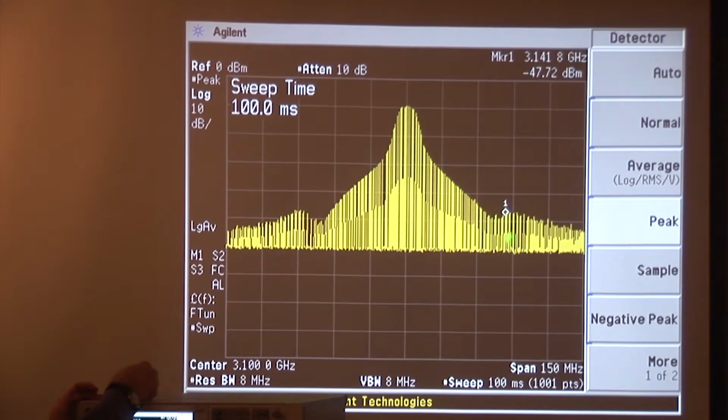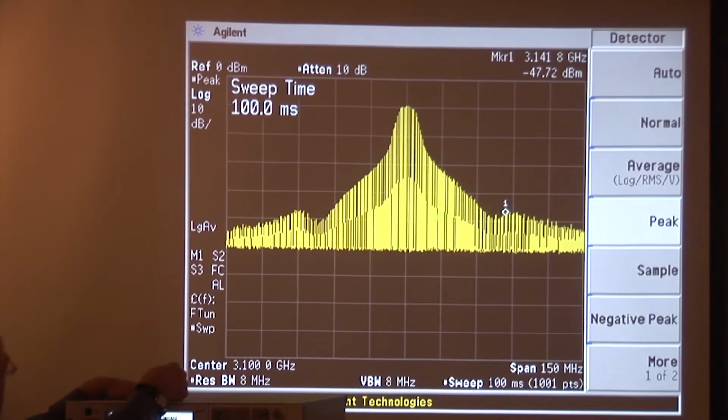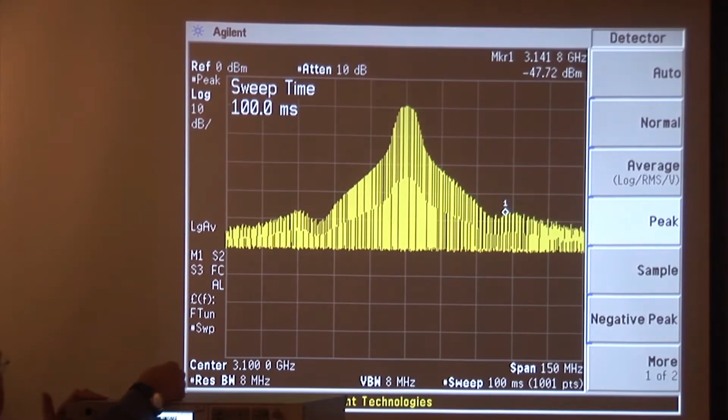And the peak detector will latch up to the highest level that occurs in any one of those bins while we're sitting there in this maximum hold sweep mode. Now, we're getting a spectrum formed up here, and this spectrum, trust me, is going to take a long, long time before it fills in completely. We don't want to see all this yellow down underneath. We want every one of these spectrum analyzer bins to be locked up to some point up in here that actually represents the radar's actual emission on that actual frequency if we're going to look at it for compliance with the RSEC. Admittedly, this is giving us some feel for what the shape of the radar spectrum is, but it's not really giving us what we want to get.